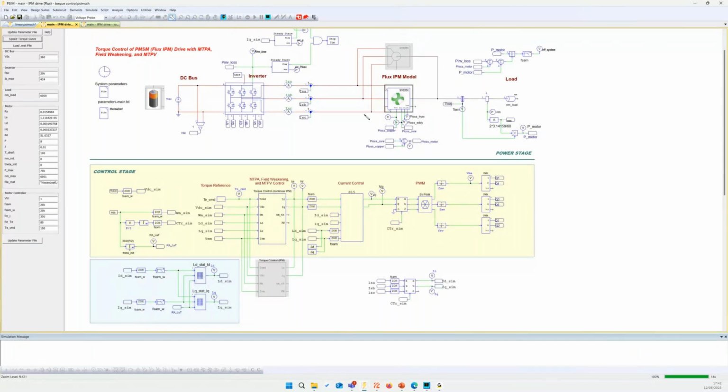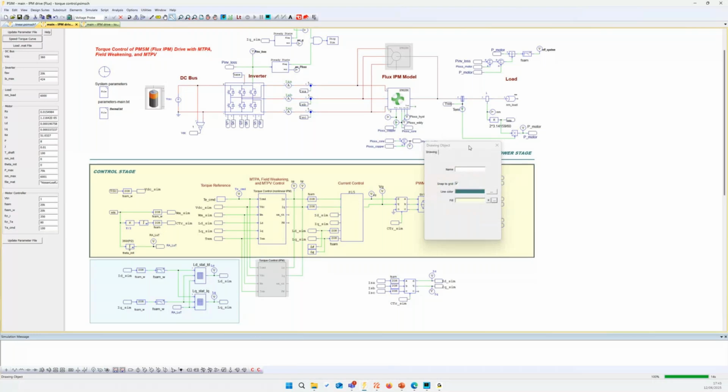Of course, I always advise that you use the reference of d-axis and q-axis current that comes from your FEA tool, if you have those, because then you will only have to tune the current control. So inside here, there are two PI controllers. PSIM offers you a way to just define the crossover frequency for the current loop and the torque loop. Basically, it reduces all the control design you have to do in one thing, but this is just to help you. This is not bypassing the complex control issues that people are facing when it comes to motor drives.